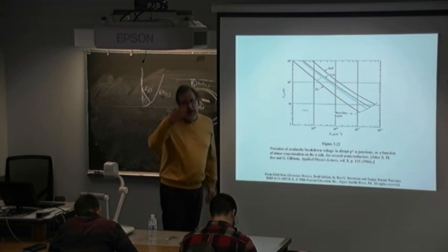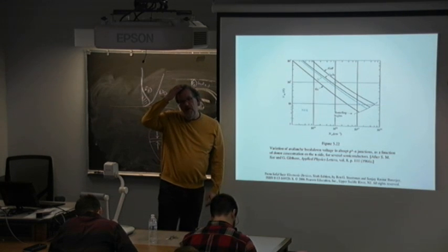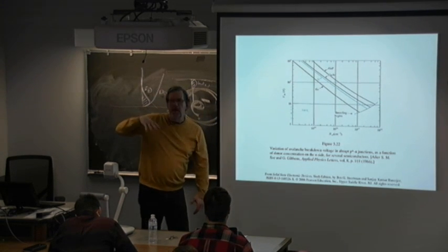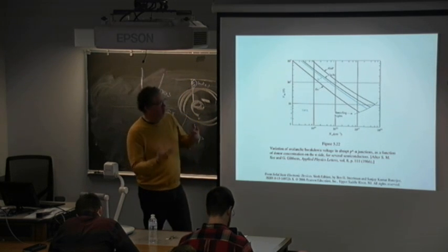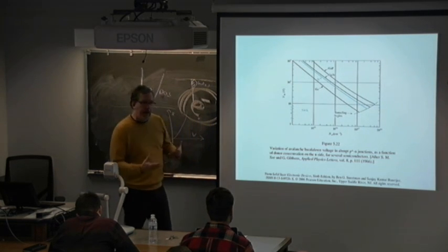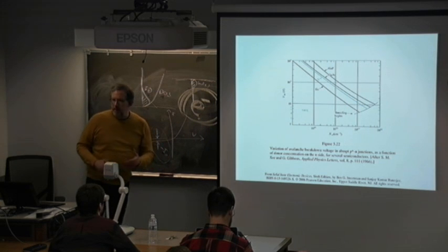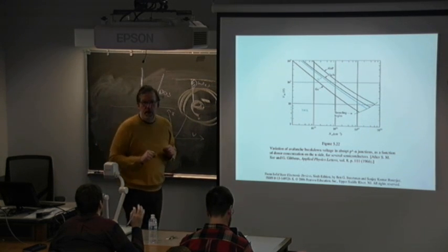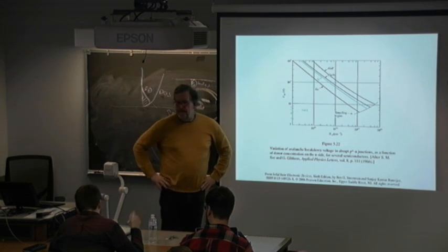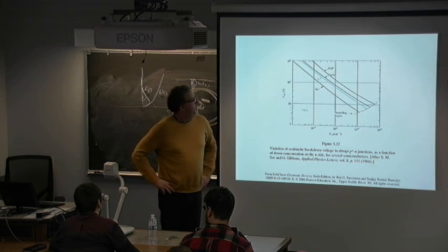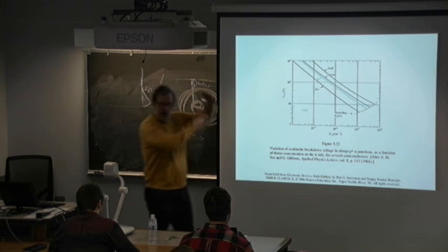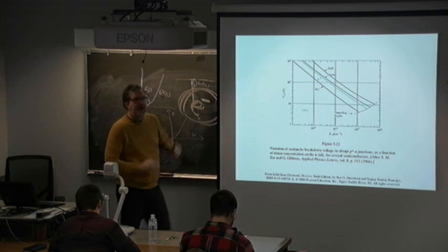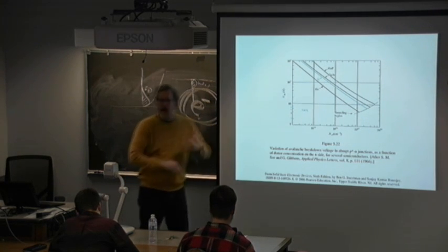So you'll see a lot of work. I have a peer faculty in our department who works on silicon carbide. And silicon carbide is great for making power switches, being able to move power around. Yes? So like a higher band gap resists the avalanche more? Yes, because it's higher energy needed to create that ionization event.